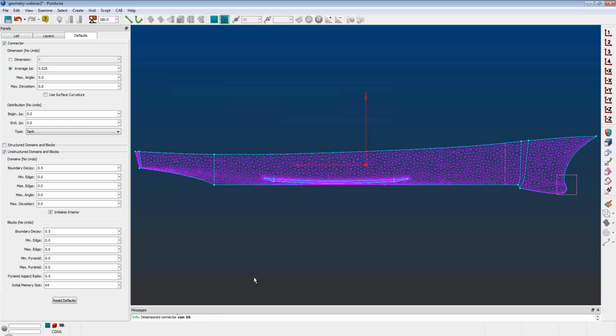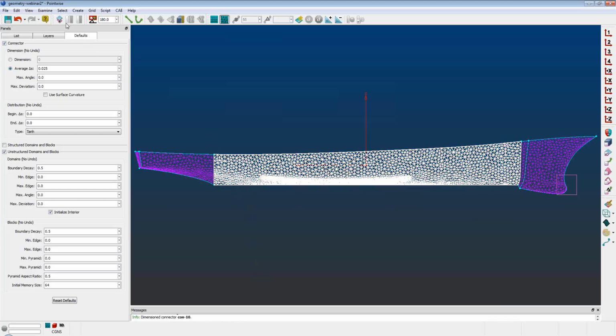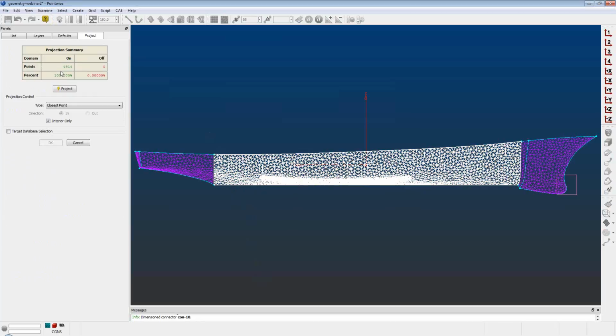So that's a very good question, Arsenio. Since you were specifically asking about some optimization or parametric study of slight deformations, say in the shape of a wing, that's perfectly fine. In that case you'd actually want to reuse the mesh and then import your new geometry every time. You would import the new geometry, import the original mesh, and then there are tools for reprojecting the old mesh onto the new surface. There's a tool we already have by default on the toolbar. It's called Project, and Project is specifically doing that.